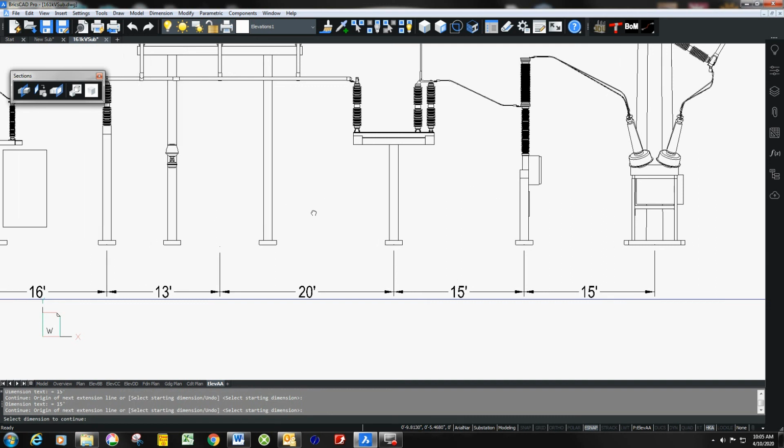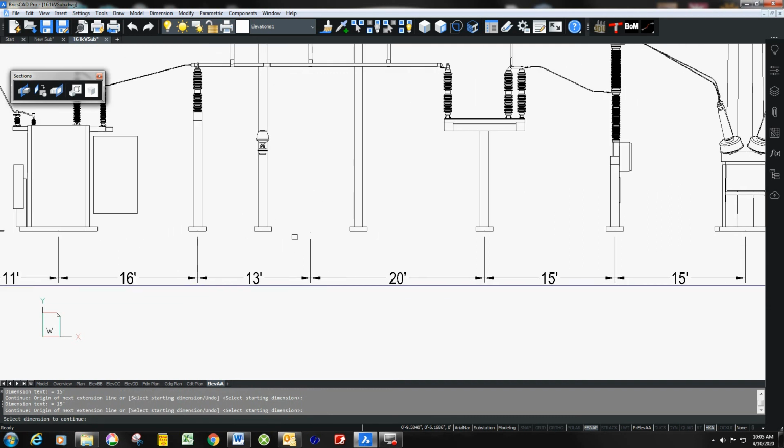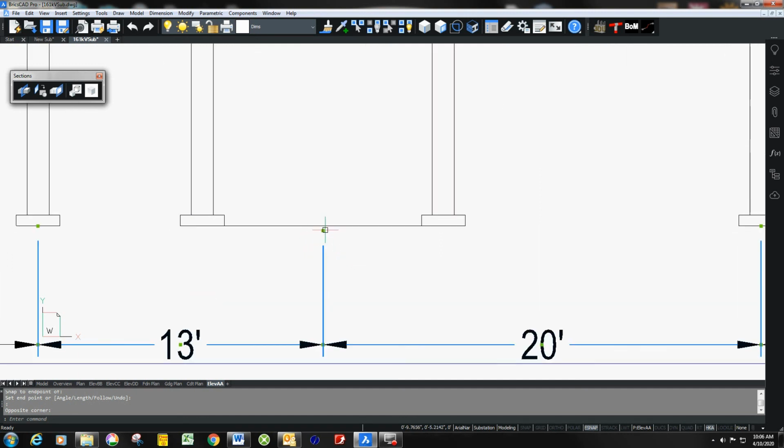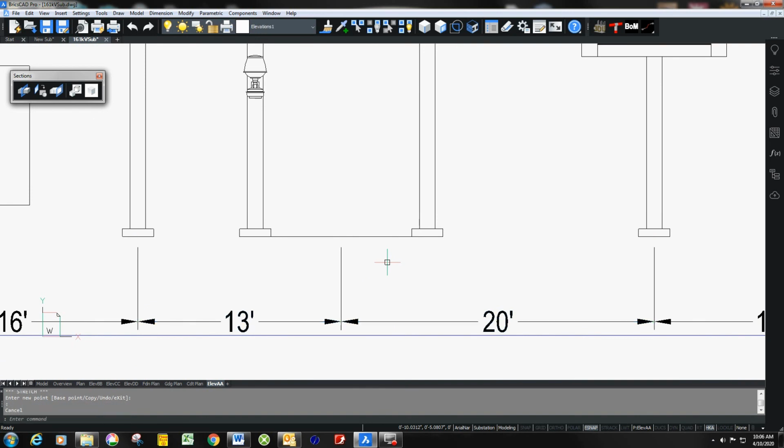We're good there. Now let me just, if I had just kind of plopped this down somewhere, what I'd have done is come back here and use the align command and go from the end of this one to the end of this one, and then I would have done a crossing select. If you want to be sure you select the line associated with both of these, go up here and grab it, and then you would just come back up here and snap it to the mid, and you'd be fine. And then do an erase last, get rid of the line.